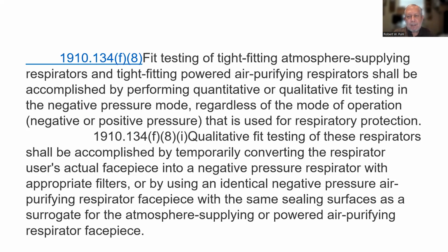Fit testing of tight fitting atmosphere supplying respirators and tight fitting powered air purifying respirators shall be accomplished by performing quantitative or qualitative fit testing in the negative pressure mode, regardless of the mode of operation, negative or positive pressure, that is used for respiratory protection. Qualitative fit testing of these respirators shall be accomplished by temporarily converting the respirator user's actual face piece into a negative pressure respirator with appropriate filters, or by using an identical negative pressure air purifying respirator face piece with the same sealing surfaces as a surrogate for the atmosphere supplying or powered air purifying respirator face piece.